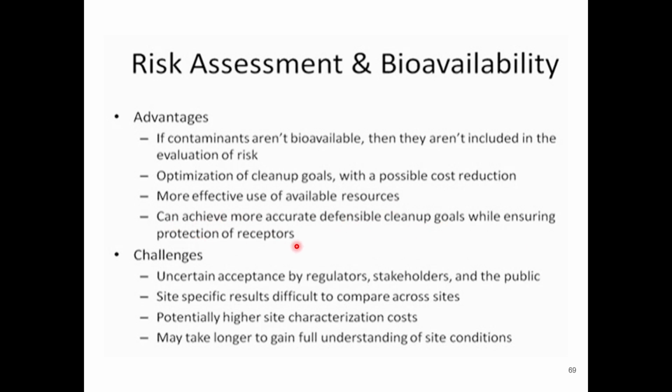ensuring protection of receptors. So basically only those contaminants which are bioavailable are selected for risk evaluation, otherwise they are not included. That results in the optimization of cleanup goals and also cost reduction, because we are very specific that it has to be bioavailable. It also results in more effective use of available resources, more defensible, more targeted cleanup goals, and protection of receptors, because we are more focused.